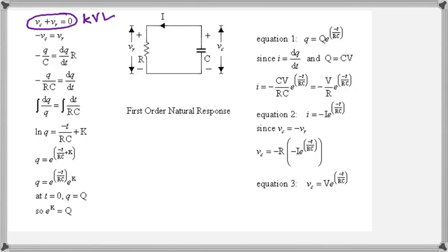And as time progresses, the small vC across the capacitor is going to go smaller and smaller and smaller till it goes to nothing and the current ceases through the resistor. Okay, so we have a voltage that's gradually decaying to zero. You can understand that because the capacitor's charge is being dissipated as a current through the resistor.